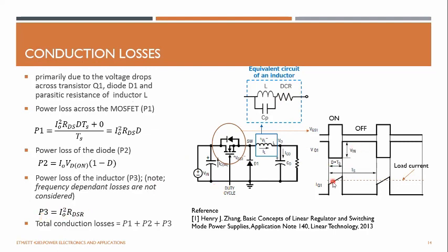If you know the average load current, the power loss of the inductor is I squared into the DC ESR of the inductor. So the inductor is heating up, the power switch is heating up, and the diode is heating up. Together, these three components add heat and loss to the system. There could be some ESR of the input and output capacitors which contribute some power loss, but that is very small. But remember, these three are the main contributors for power loss of a buck converter.